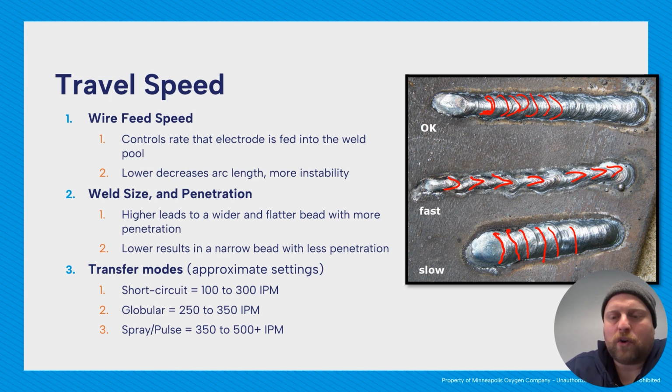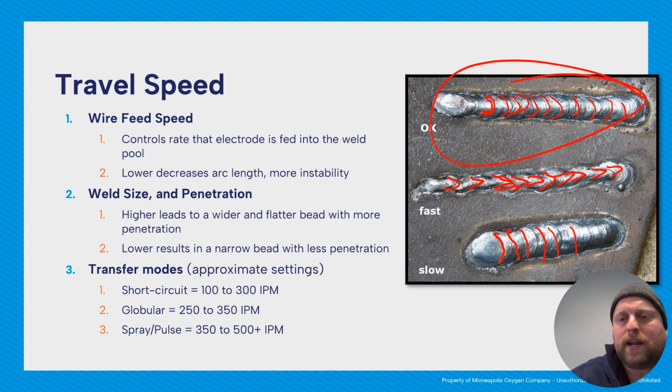So if you haven't done it before, when you're welding and you start to get pretty proficient, you'll be able to read what's going on while you're doing it and adjust these variables. For instance, if I was welding and I'm seeing that my bead has these points, I'm going to slow down, try to get it to what it's like up here. If I slow down too much and it gets wide, I'll speed up. Again, try to get up here the entire time.